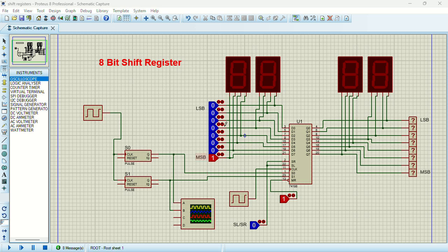So here I have this value, which is going to be 80 hexadecimal. These displays are going to be showing my values in hexadecimal, by the way. So this value is actually 80 hexadecimal or 128 decimal. Okay. So I'm going to be storing it in the shift register, and then I'm going to shift these bits to the right 7 times. Once I'm done, my final output should be 1, because 128 is 2 to the power 7. Since I'm shifting this value 7 times to the right, I'm essentially dividing it by 2 to the power 7. If you divide 2 to the power 7 by 2 to the power 7, you simply get 1. Okay, so let me just run it and show you guys what I mean.